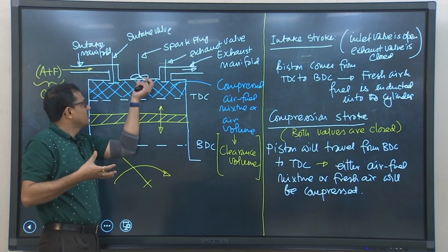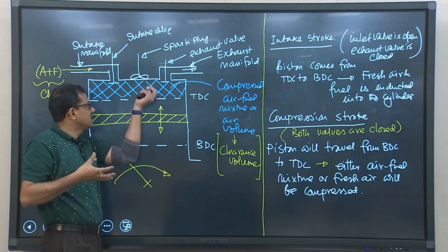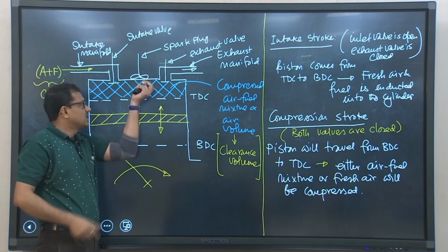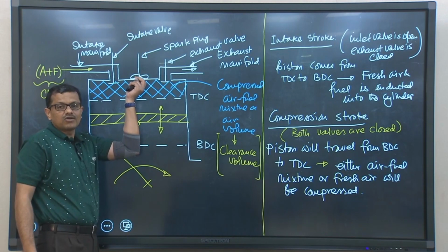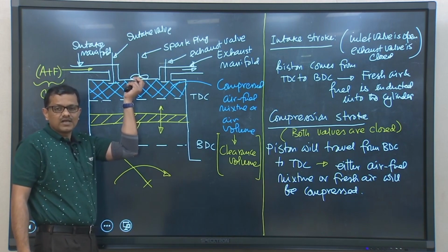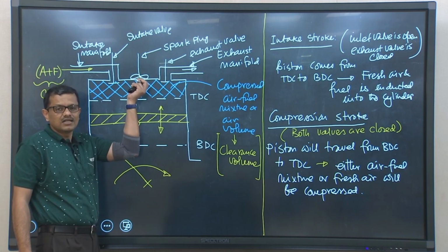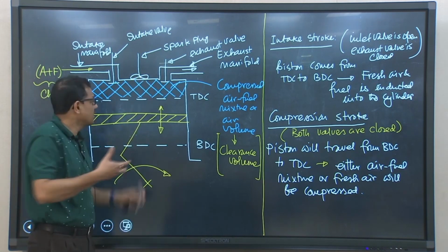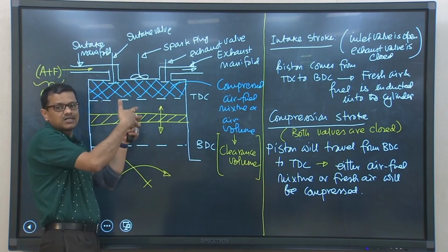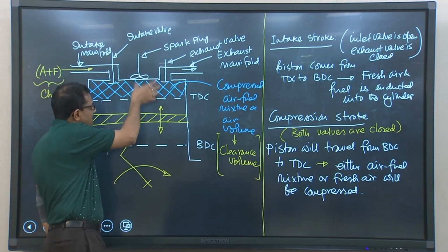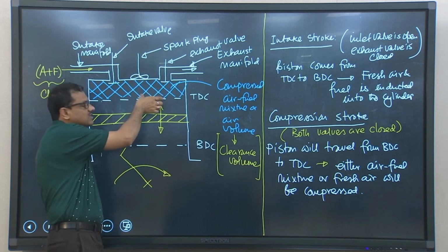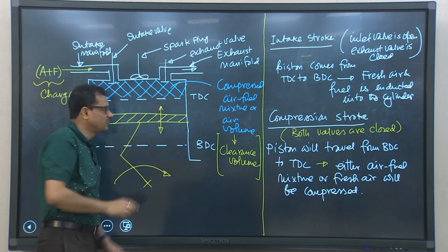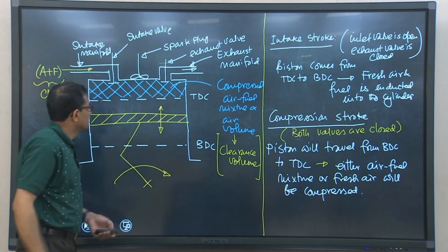So, when the fuel is sprayed inside this engine cylinder, and to be precise in this particular space where compressed air is there, and that compressed air temperature and pressure is so high that the moment fuel is sprayed it will ignite, and because of this self ignition, auto ignition, entire combustion will be completed, and as a result the thrust that is produced will allow the piston to go back from TDC to BDC, and that is related to the CI engine.